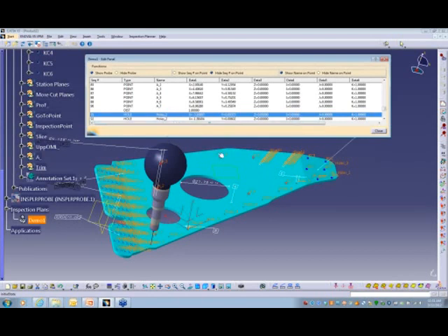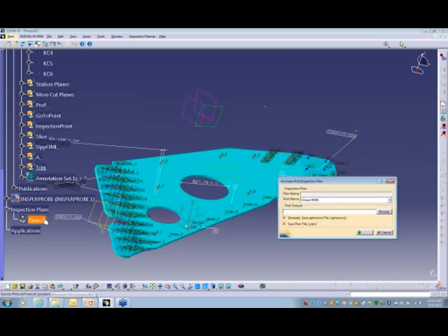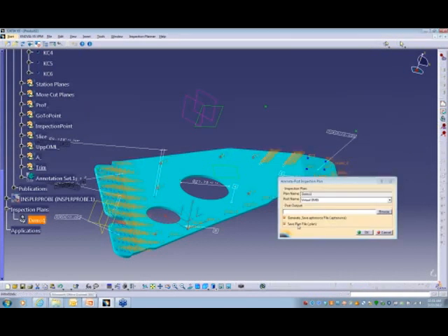At this time, we want to post-process this for our CMM, to give it to the CMM operator. We're going to come up here. We're going to hit post-process. We're going to post-process the demo file. We output an APT source file. Some of our large OEM customers use Vericut, and they wanted to simulate to do their collision detection using Vericut. Any NC programmer on this call will know exactly what I mean. There's a good chance you use Vericut if you're programming in CATIA.